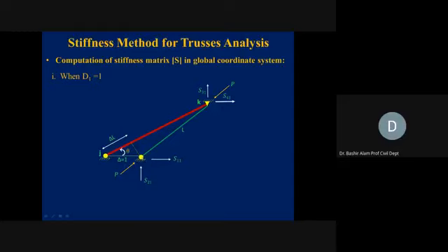So it is coming to this right roller location. And this green one you see is becoming the length of this member. Obviously this green length is less than this red one, which was the original, meaning this member, by this sliding activity, is coming in compression.